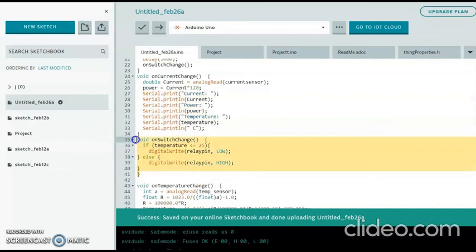And then in here, this is my specification for the relay and controlling the heater. Since I cannot connect my code and my components to the dashboard and actually control the heater from the switch on and off from the dashboard, alternatively, I set the specification for the code so that the relay turns on when the temperature is below 25 and turns off when the temperature is over 25, so that I can get a stabilization point between 24 to 26 Celsius. And yeah, this is pretty much the alternative of controlling the heater in just an automatic procedure.